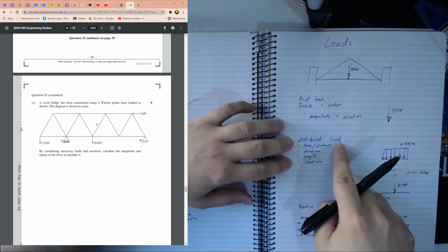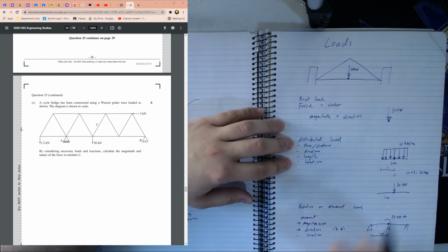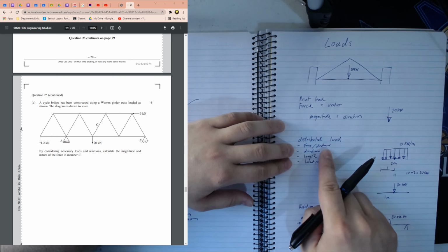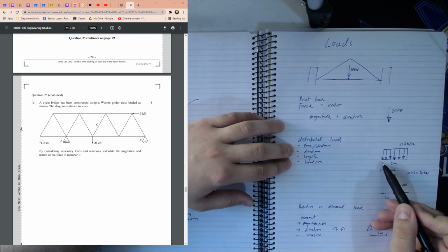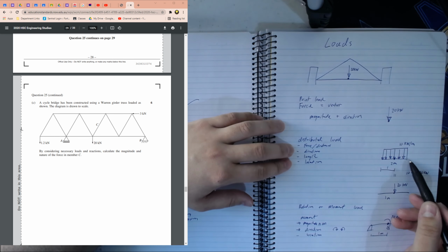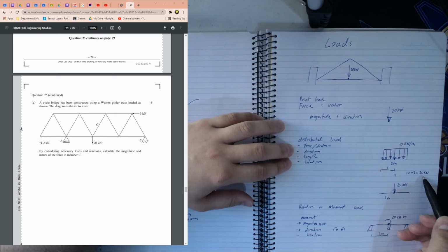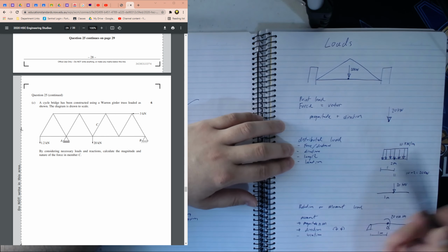We could get distributed loads, which look like this, which is a load that happens over a distance. So this could be like the Harbour Bridge having multiple different cars. It is a force and a distance. Over here we have 10 kilonewtons per meter, so if we go 2 meters, we can find out the total force because it's 10 kilonewtons per meter times 2 meters equals 20 kilonewtons. They also have a direction, a length and a location.